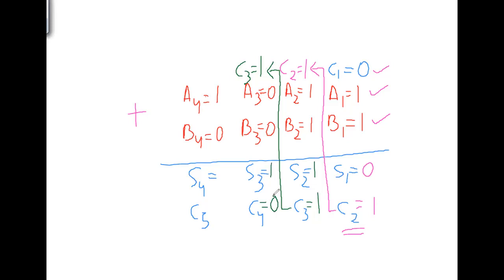Then we have to shift this C4 to the next bit. I have to do like this. So here C4 is equal to 0. Then I have to add these three numbers. What are the three bits? C4, A4 and B4. If I add, then 0 plus 1 plus 0 is equal to 1 with carry 0. Understood? Now I'll stop here.